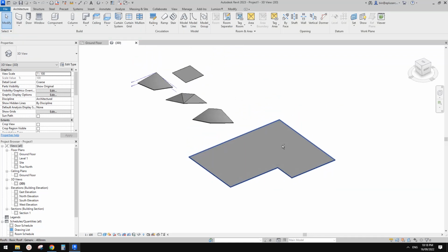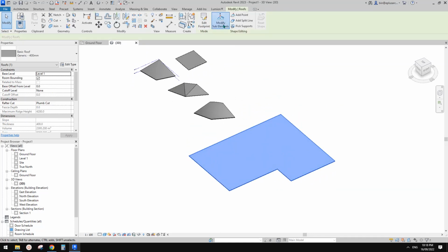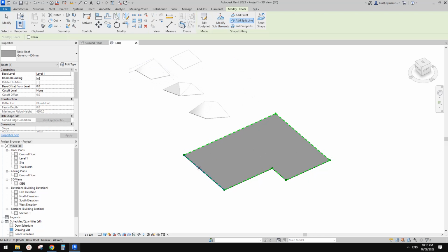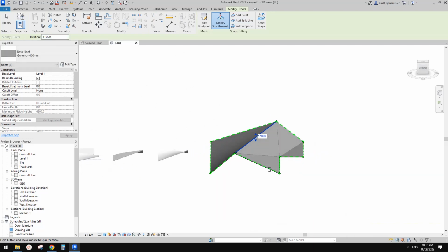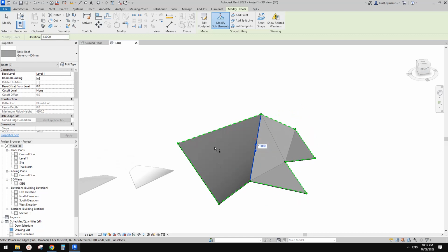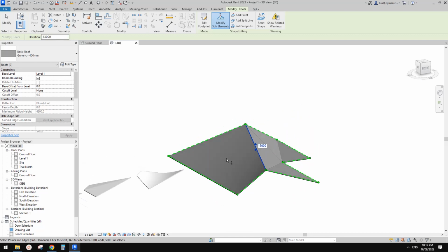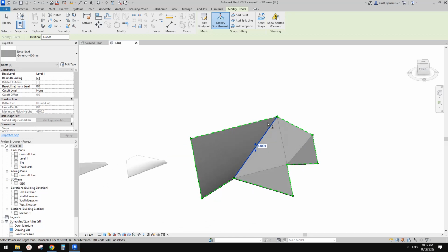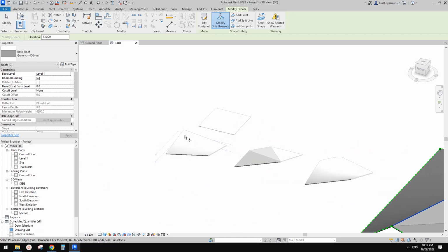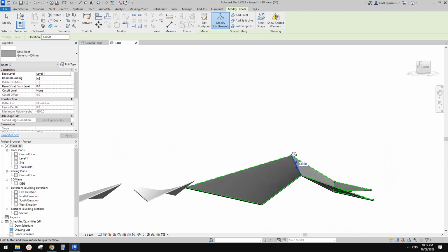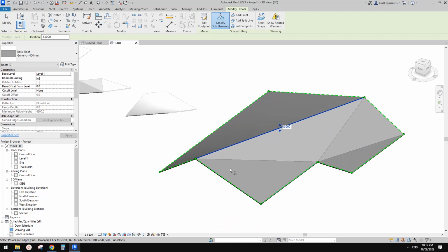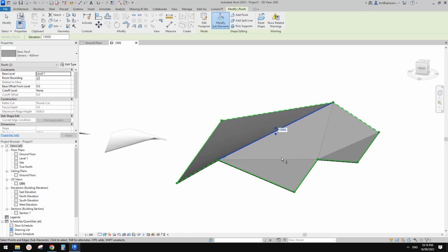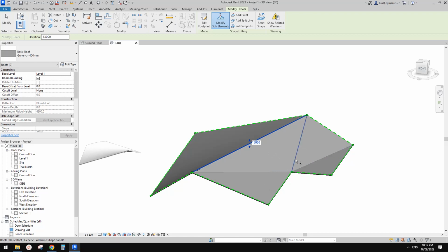So now I want to maybe add some split line between them. So for example, I want a ridge here. Okay, so now we can select this one, go up, right? And you can see, because this surface becomes curved, because there's 4, 1 2 3 4, just like the 1 2 3 4. So Revit created this curved surface, but here, because we have 1 2 3 4 5, we have this flat surface with split line between them.